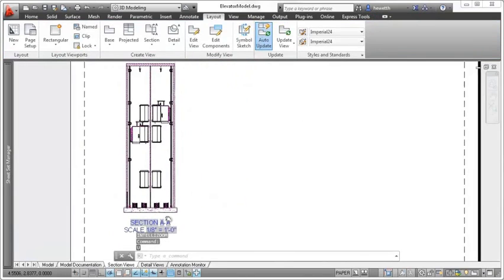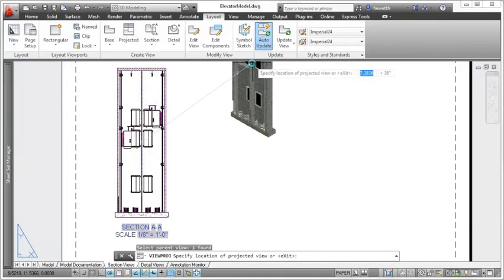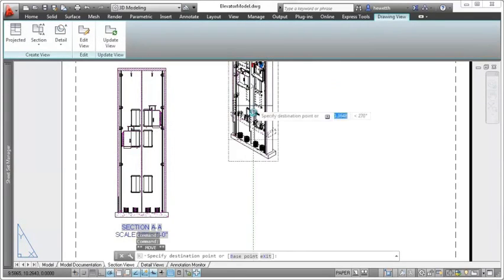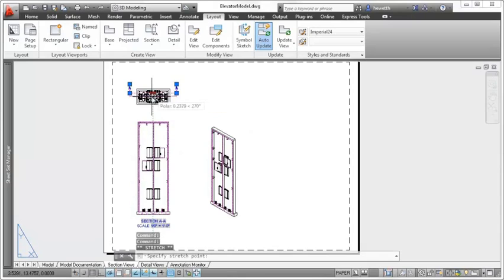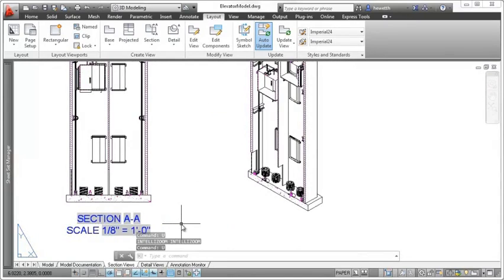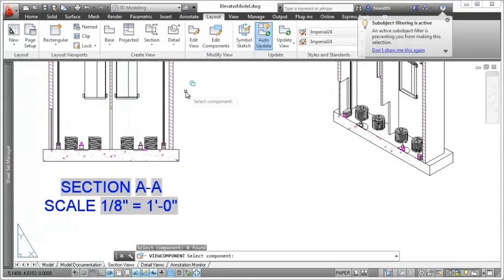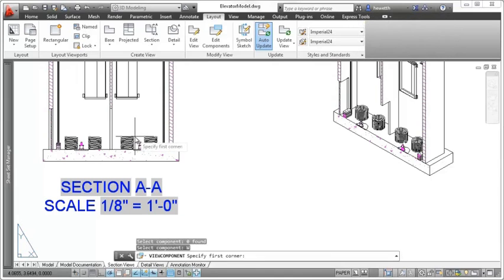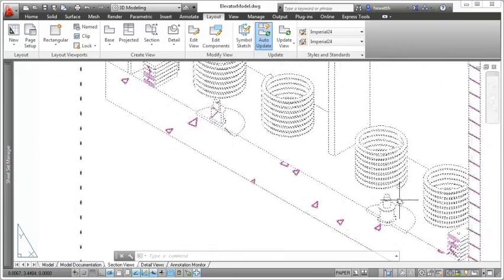If you project a view from a section view, it takes on the properties of the section view and maintains associativity with it. If, for example, the section line changes, the projected view updates accordingly. When creating and editing section views, you can control whether individual model components participate in the section using the Edit Components tool. If the selected components are set to none, the components display without being sectioned. The participation of components is passed to the views projected from the section view.